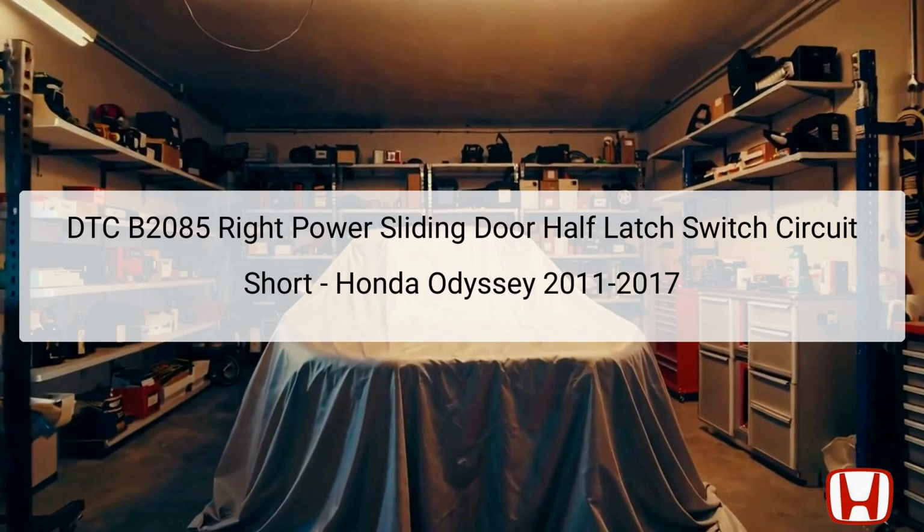The diagnostic trouble code DTC B2085 indicates a fault related to the right power sliding door half-latch switch circuit in the Honda Odyssey model years 2011 to 2017. This code usually points to a short in the circuit that can affect the operation of the power sliding door mechanism, which is an electric system designed to provide easy access to the rear seats.